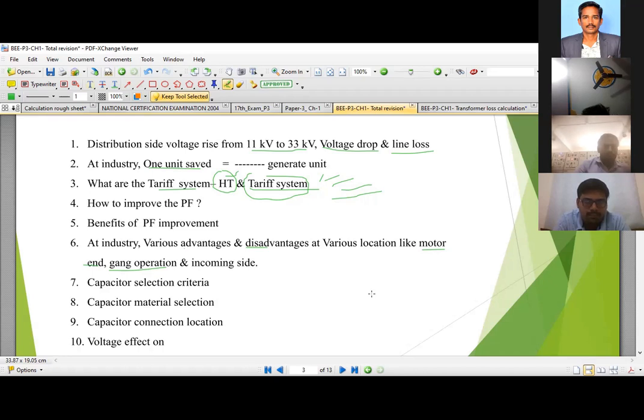This is the main disadvantage. Installation cost is less, but we cannot separate it for 5 motors in gang operation from the other motors. Maybe if we use a 2 bus and 2 incomer method, we can connect separate reactors, but it will not affect the already installed gang for 10 motors. Then installation costs reduce and investment costs reduce. That is 2 benefits. Disadvantage, we cannot rearrange this.